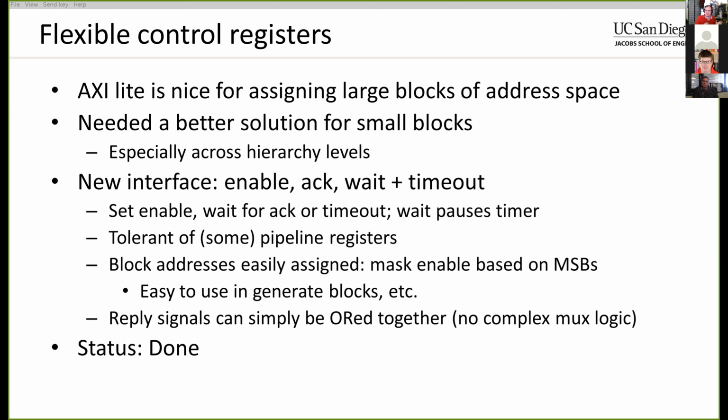This doesn't work so well if you're using AXI Lite interconnects, because you have to add another port, and you have a bunch of muxing and arbitration logic. And generally, all the address decoding has to be based on powers of 2, and it can't be overlapping. So I can't just pass one register through. It becomes a real mess. So I did some thinking.